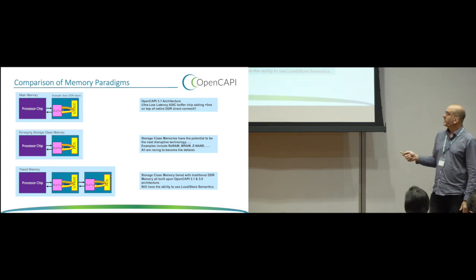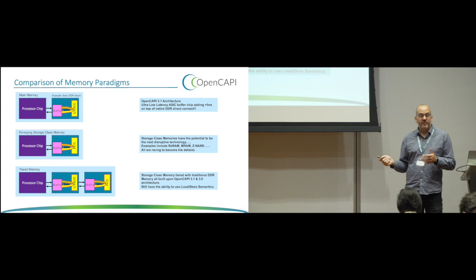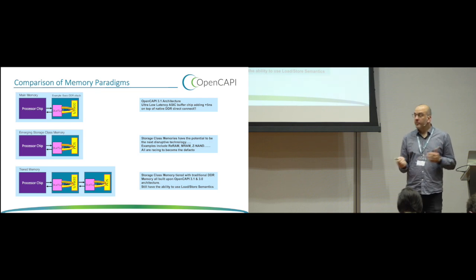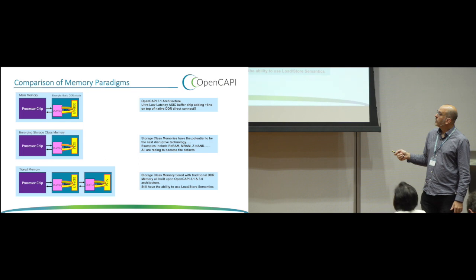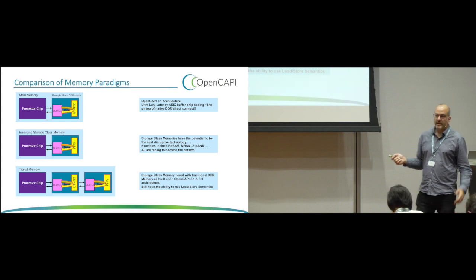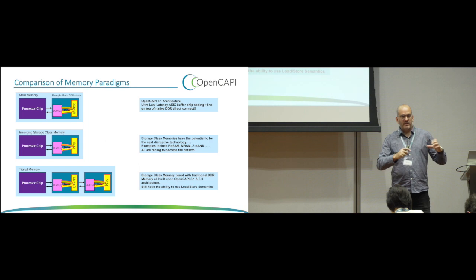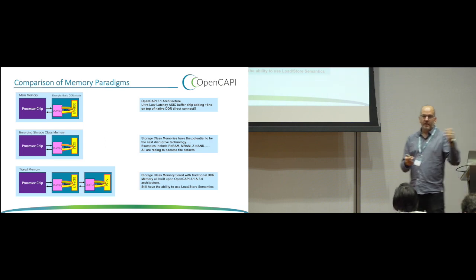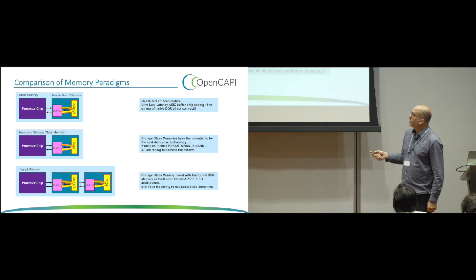And so if we can start to get to SCM and other types of devices, we can buffer up writes. Maybe they are not yet persistent, but they've been acknowledged by the controller, and we can put some amount of capacitance on the controller, or maybe it's in its own power domain, right? So this is a connector, or it could be a cable. So the memory device here could actually be in some other appliance sitting next to the processor that you're doing loads and stores to, right? That other box has its own power domain, and so as soon as the write makes it across, the other box can acknowledge it, the processor could fail, and we've had a very clean handoff of the write across the interface. So that's like a storage class memory.